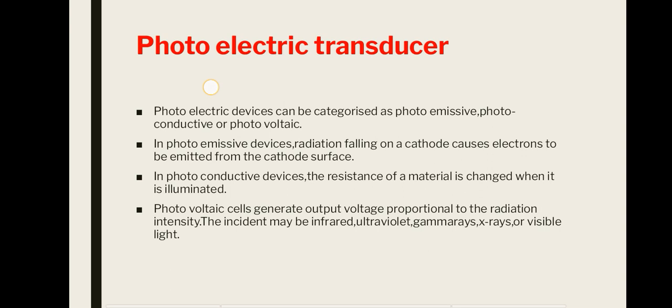Each dynode is at a higher voltage in order to achieve the requisite electron velocity each time. Hence, secondary emission and resulting electron multiplication occur at each step, with an overall increase in electron flow that may be very great.